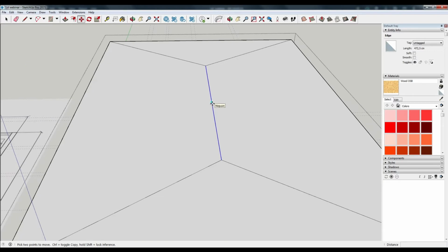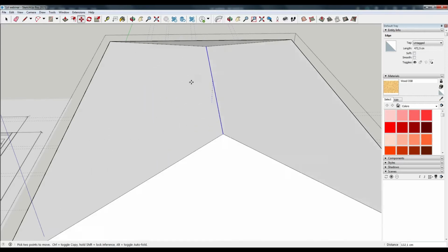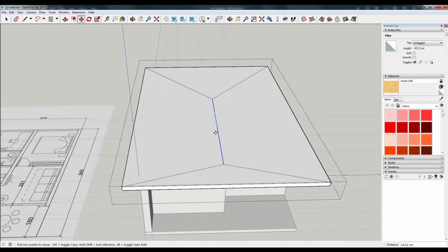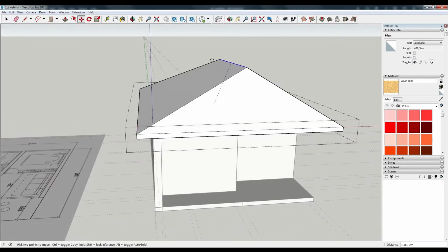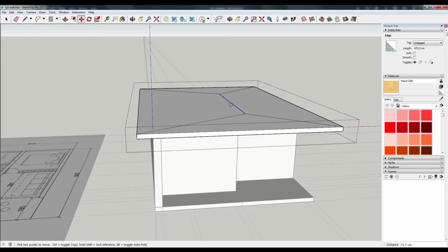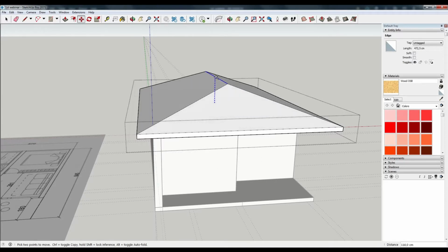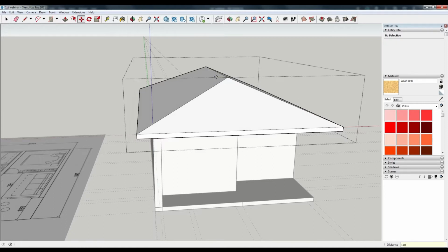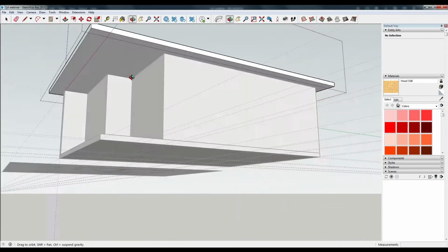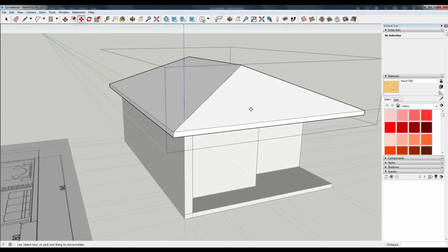I choose the Move Tool and I choose the middle point of the middle line in the center of the roof. Then I click on the keyboard with the up key to show the direction, because otherwise it would be difficult to choose the direction. Now I will give my measure. My size would be 140. Now I have a 3D roof.